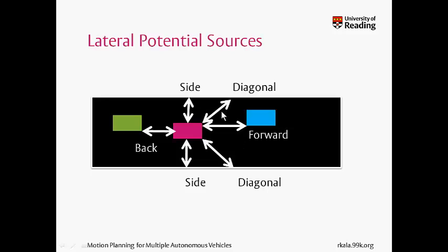Now, since I have said that I will be only taking potential from 6 of these, the only source of repulsion would be these 6 obstacles that I have taken out here, or obstacles in the 6 directions that I have taken out here. Next, as my design methodology, I say let me take each and every obstacle separately. So I'll first study this thing. I'll say only imagine that there was a vehicle out here, a blue vehicle out here. Do not imagine the road boundaries, do not imagine the other vehicles, do not imagine anything else, and simply decide what you would have done.